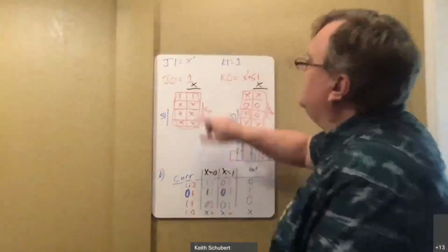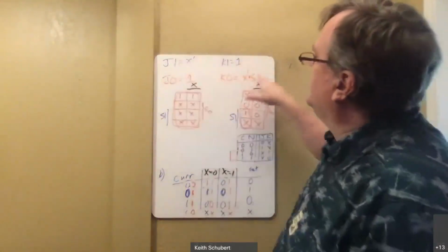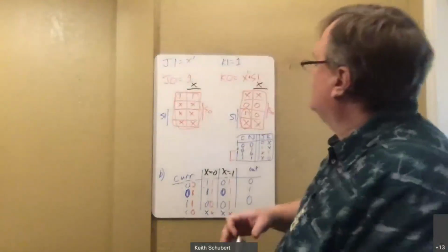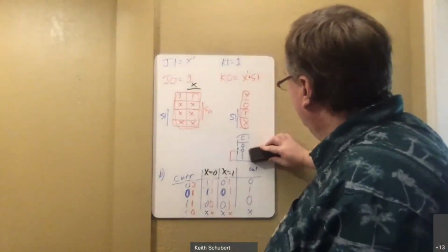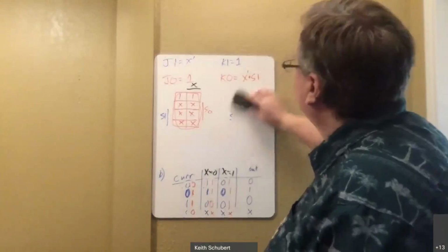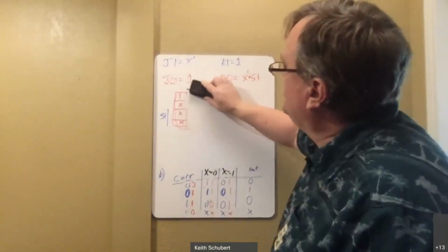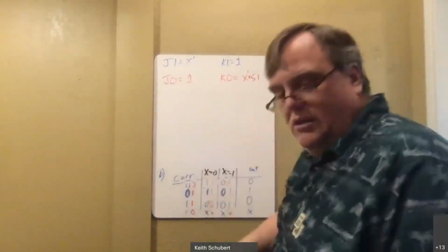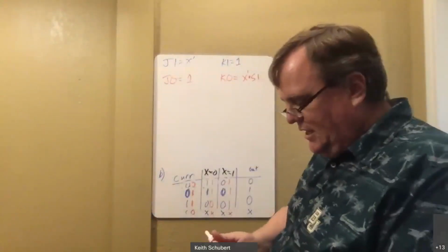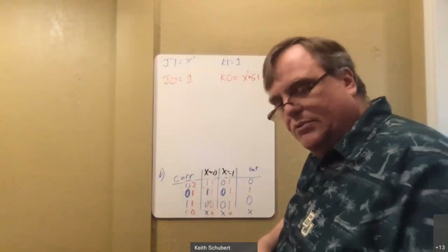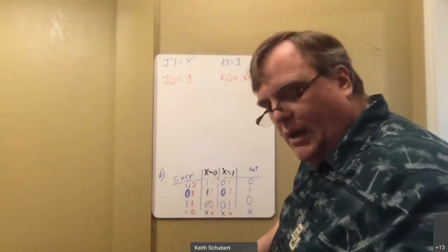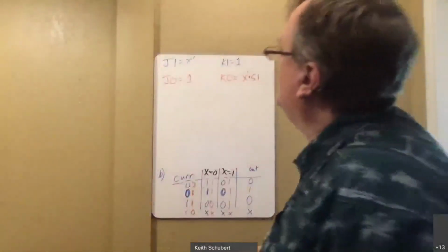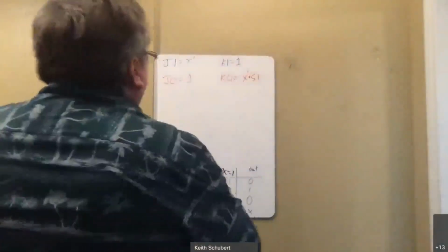I don't need these anymore because all I was trying to do was get these equations. I now have those equations, so I don't need anything else. I can now just draw my circuit. I don't need the excitation table either because I only use the excitation table to fill out those lovely JK K-maps. I'm going to draw my circuit just all using a black pen if that's okay with you. And I'll just label them.